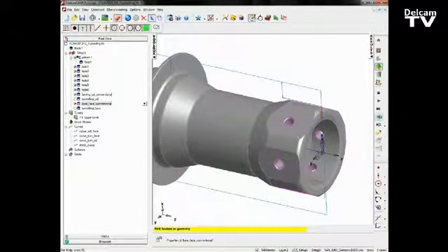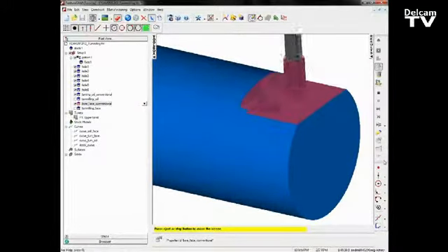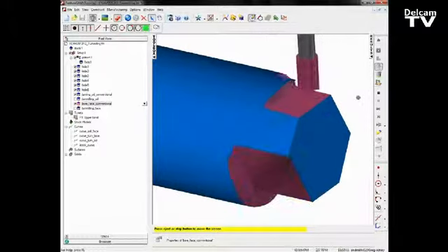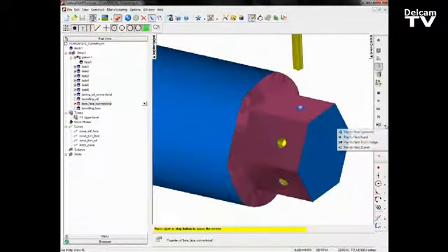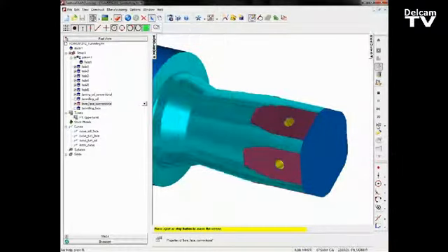And again, playing the simulation. Again, just going to increase the speed slightly. So we'll work our way around, drill all the holes, play the next operation, play that turning operation, then we come over pre-drill, and then we use the boring tool to bore out the material, like so. So what we're going to use instead is turn milling.